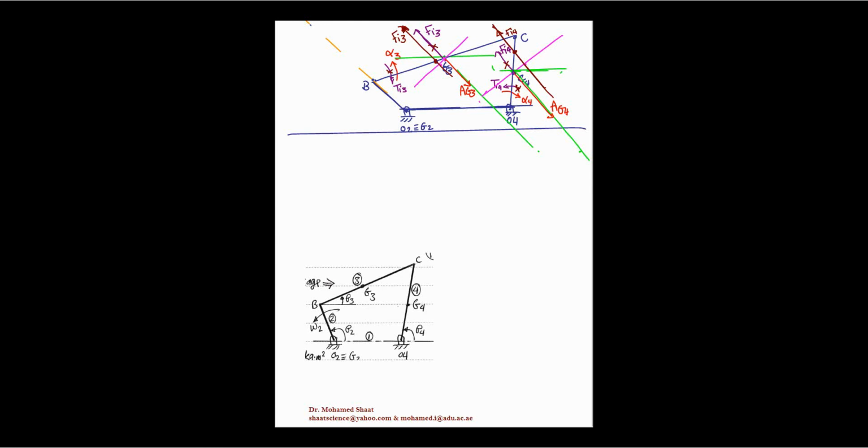Then we're gonna identify the direction of the torque and the inertia forces. Then we're gonna combine them in one component over the same graph. Make sense? Till the moment we didn't do any force analysis. Make sense? Then we're gonna move to the next step. The next step is just to apply the superposition analysis method to do analysis for the different elements.